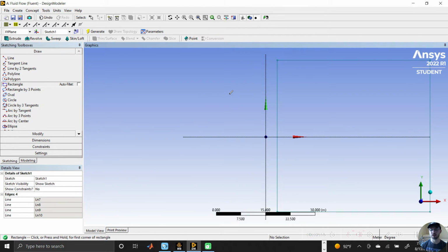However, we're modeling airflow in the atmosphere. When you're in that situation, the flow is turbulent, and essentially what that means is the air coming at the airfoil is coming in from all directions. To make sure that we model that as accurately as possible, instead of just using a rectangle, we're going to model the front, which will make the inlet boundary for the air coming in to the front of the airfoil with a very large arc coming around the front.